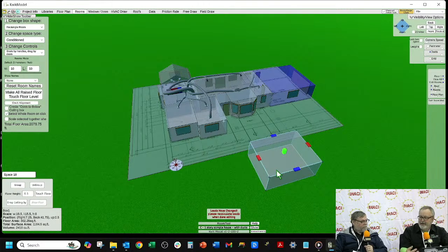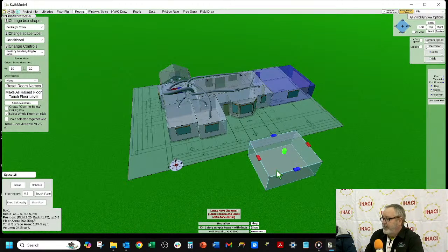You're guessing. And the way I explain it to contractors is, there's an old saying for carpenters that you measure twice and cut once, right? I'm not a professional carpenter, so I usually measure once and I end up having to cut twice. If you're not doing a load calc, you're not measuring at all. You're guessing on the size of the equipment. Right. You're using square footage or something that makes no sense. And honestly, I don't know how people can call themselves professionals when they do it that way.